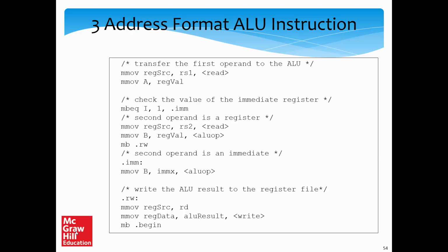So now the important point, of course: a large part of this is very, very straightforward, just moving things around. But the important point is an instruction of this type. So recall that two things are being done here. First, we are setting the contents of reg source to the contents of rs2. That is one thing. In parallel, I remind you, simultaneously, concurrently, we are also accessing the register file.